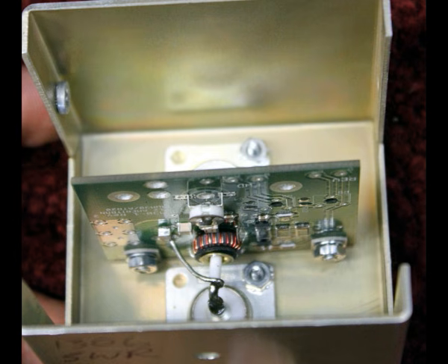But this measures the vector sum of the voltage across the transmission line at the point it's inserted and the current through the line at that same point. So it sums these two at radio frequencies. It just sums the two things right together. One direction it adds the two quantities, the other direction it subtracts the two.